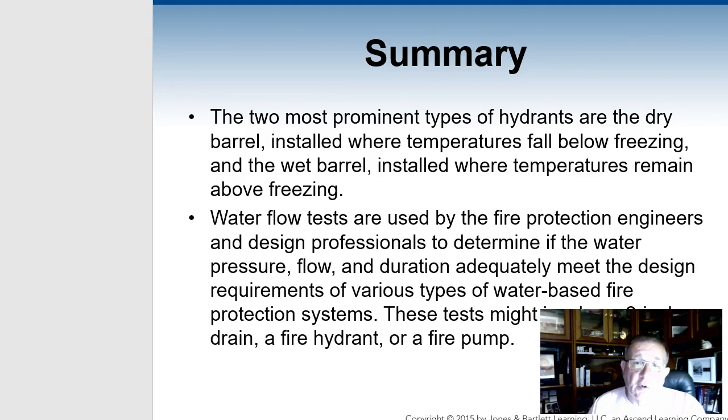So the two most prominent things in any of this is the hydrant itself. Is it a dry barrel or is it a wet barrel? The other part of this is the flow test. Are they being done by fire protection engineers? They give the calculations and then you accept it, and guess what? Then it has to be maintained at that accepted level at all times.